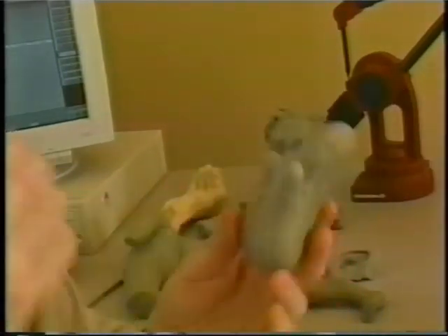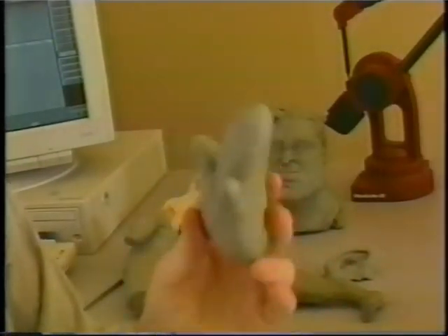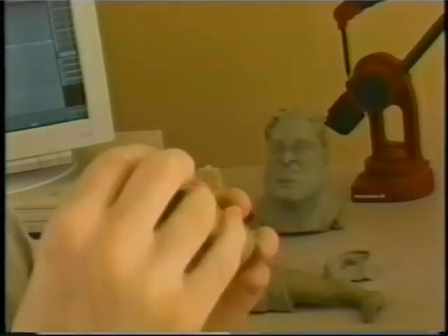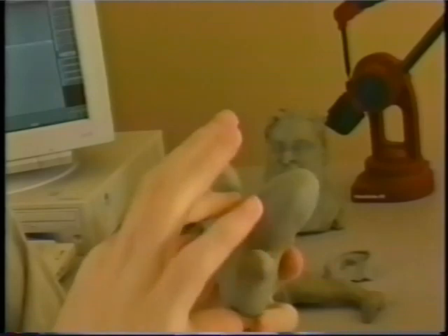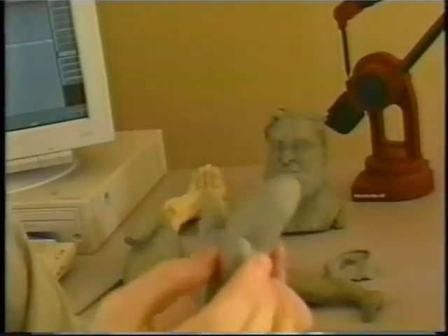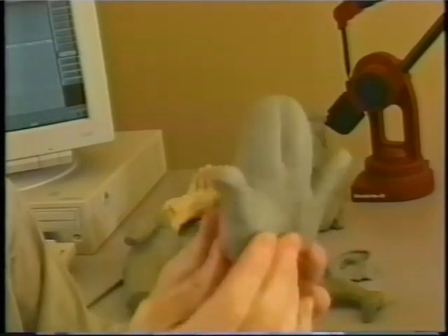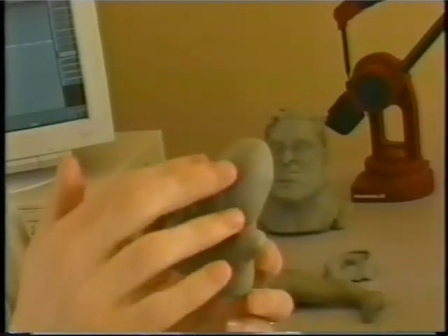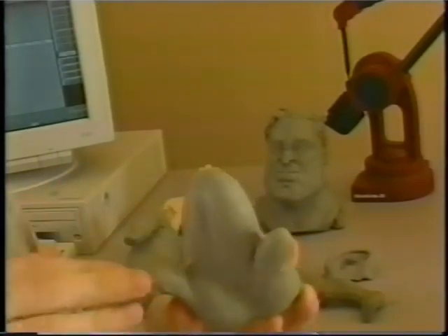Okay, this next shape is very complex. Has 3 points to it. How would you realize this in NURBS? Well, the way I did it was start one pole here, spread out, and then wrap around to the thumb. So that way there aren't two surface connections for the pinky and the thumb. There's just one for the pinky. Geometry flows down, wraps around, and up the thumb.